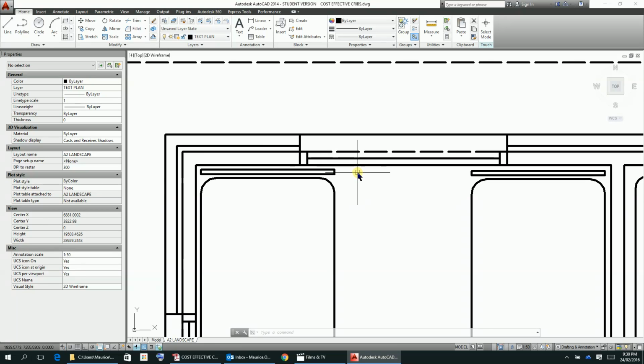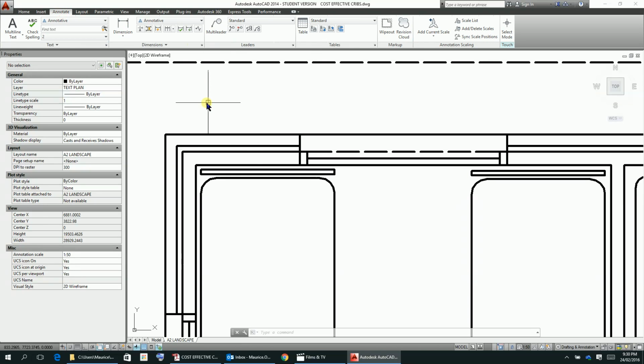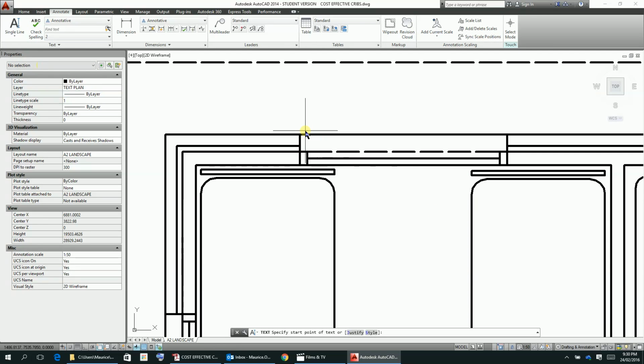Alright, so now let's have a look at this window here, 1200 times 1400. Probably, as I'm doing a lot of text, go into the annotative thing there. Multi-line text. I want to go with single line text for this one here in this particular instance. It might pay to turn off the snaps here. So turn off there so that it's not snapping into the line. We've got a bit more control there. It would possibly be helpful to have the ortho mode on, because that's how we'll be working.